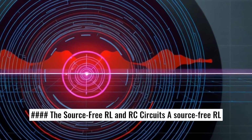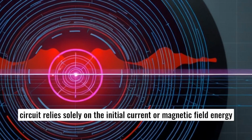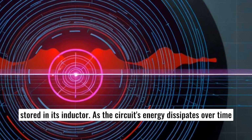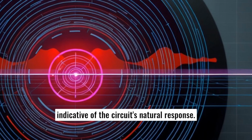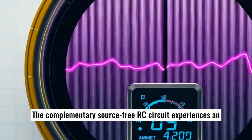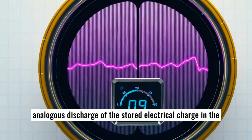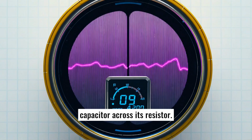The source-free RL and RC circuits. A source-free RL circuit relies solely on the initial current or magnetic field energy stored in its inductor. As the circuit's energy dissipates over time through the resistor, the current decreases exponentially, indicative of the circuit's natural response. The complementary source-free RC circuit experiences an analogous discharge of the stored electrical charge in the capacitor across its resistor.